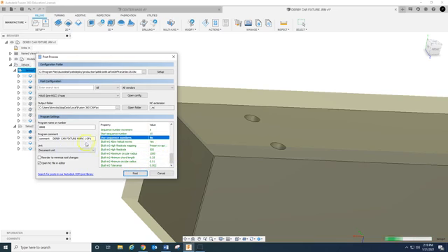And then all this built-in tolerance, all that stuff, that's probably not what you think it is. A lot of people think, oh, I got a tight tolerance part, let me set this to 50 trillionths. That's not going to do what you want it to do. About 2 thousandths is about where you want to put that. If you need to hold some really tight circular stuff, then you can always set it a little tighter, but it's going to slow your code down.